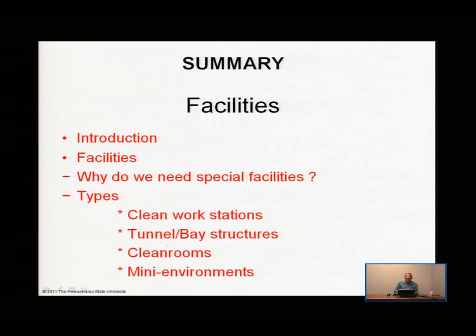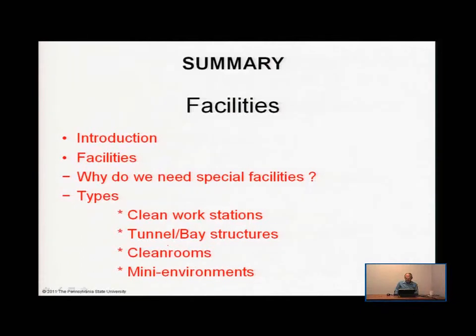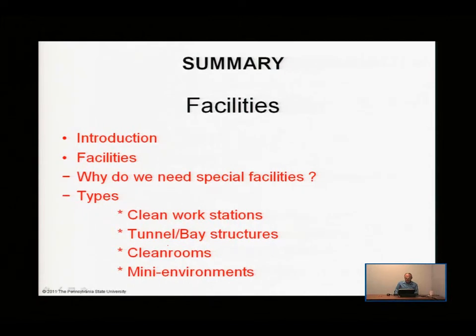And then we talked about tunnels and bays, where we assembled workstations into a volume in which we then controlled the contamination. The reason we were driven to look at this tunnel bay idea was we realized that often we may need to move products from workstation to workstation as they proceed through the processing flow.